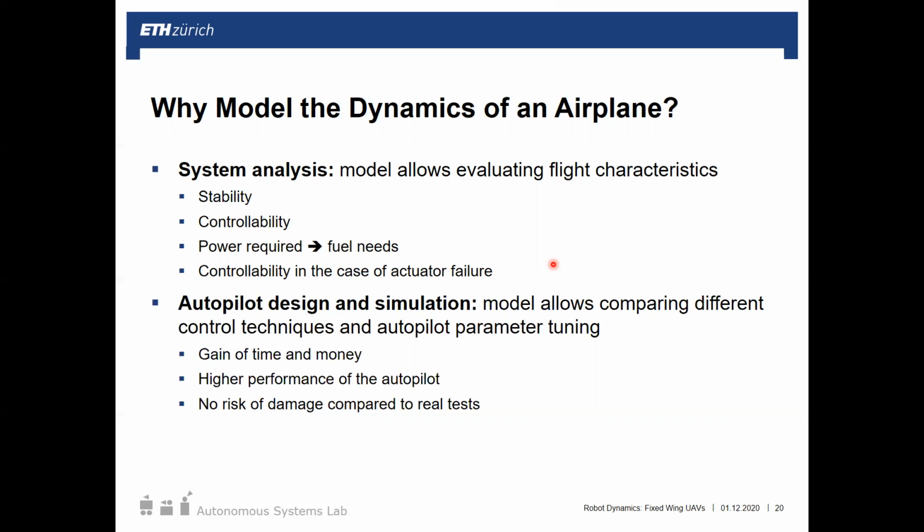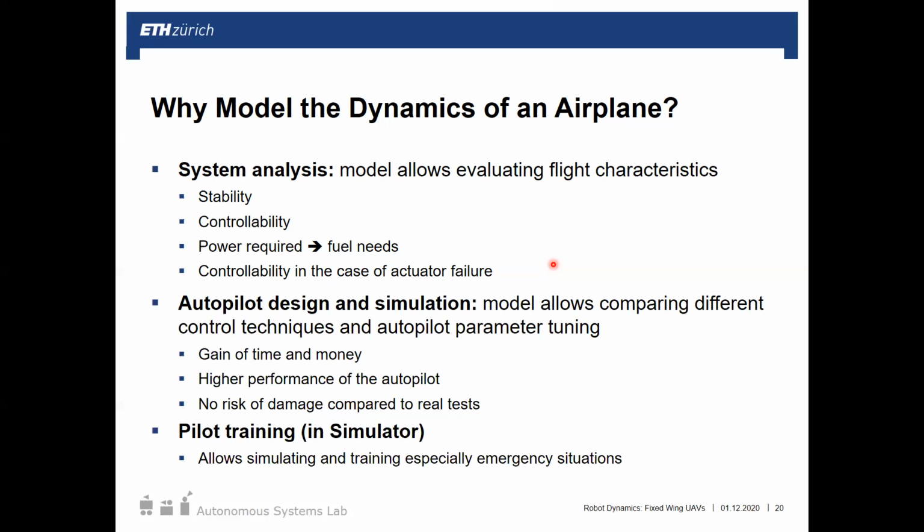Every test outside is a bit risky. If anything is wrong in the code, then it could be catastrophic in the end. So you can normally save a good amount of time by doing some parameter tuning, state machine testing, and functionality testing in simulation first, and then going outside later.